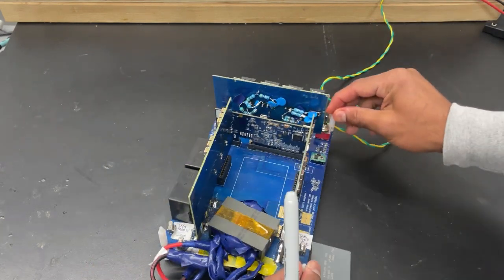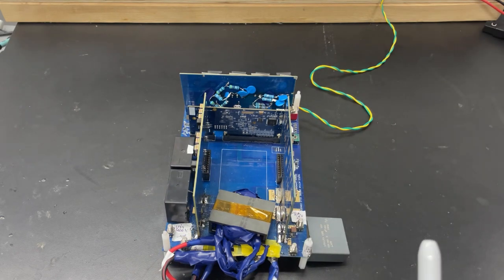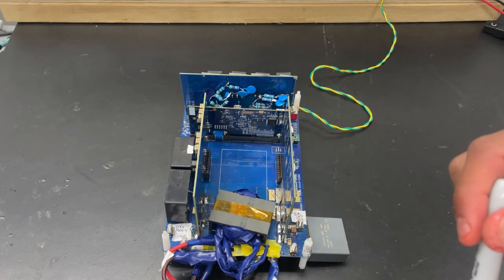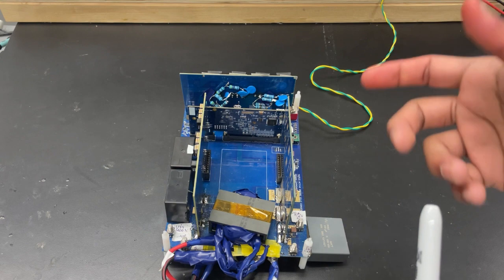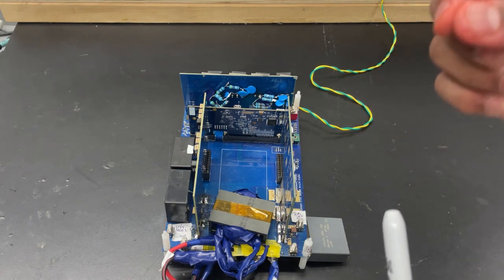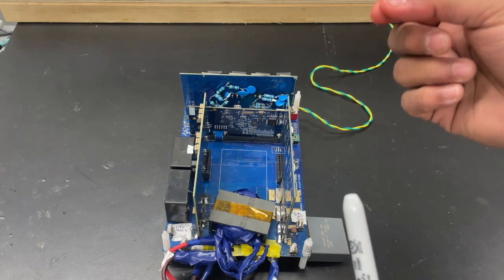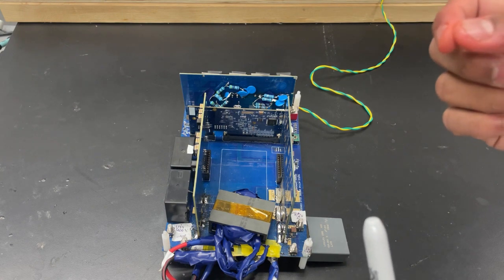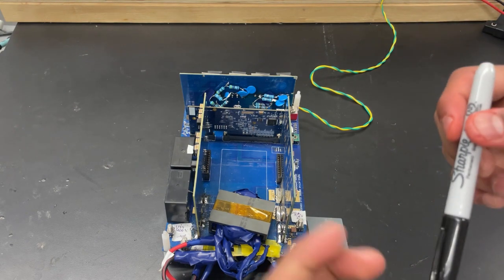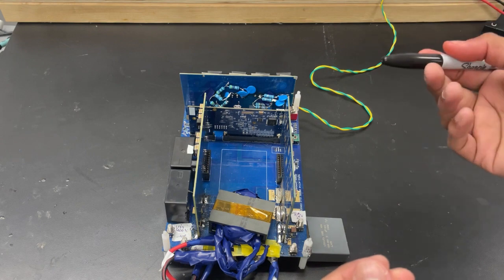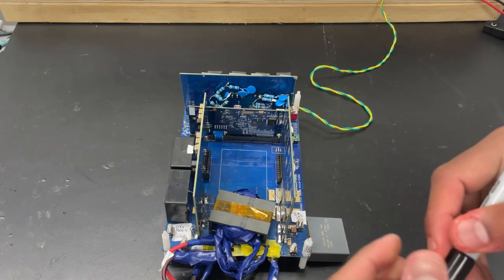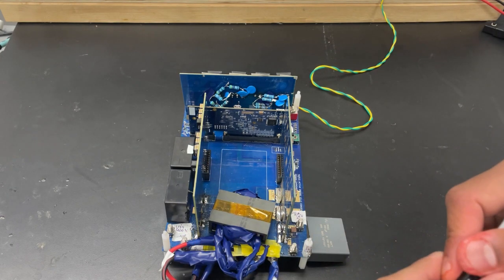The final part of this particular hardware description is the 3-winding transformer. This particular 3-winding transformer was wound by me. The turns ratio on the primary side is 16, the turns ratio on the secondary side is 22, and the turns ratio on the tertiary side is 1. So that concludes the hardware description. Now we'll move ahead to the hardware testing of this particular converter, and we'll share the results.